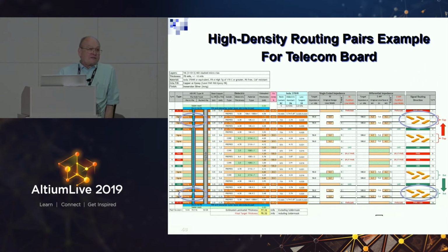So it's not just me. One of my companies I consulted with, this is Cisco. This is actually a copy of a Cisco PC board. And you can see up here that I've circled how Cisco has specifically adopted a horizontal vertical two-layer routing strategy here and here. And those will always be their most sensitive nets.